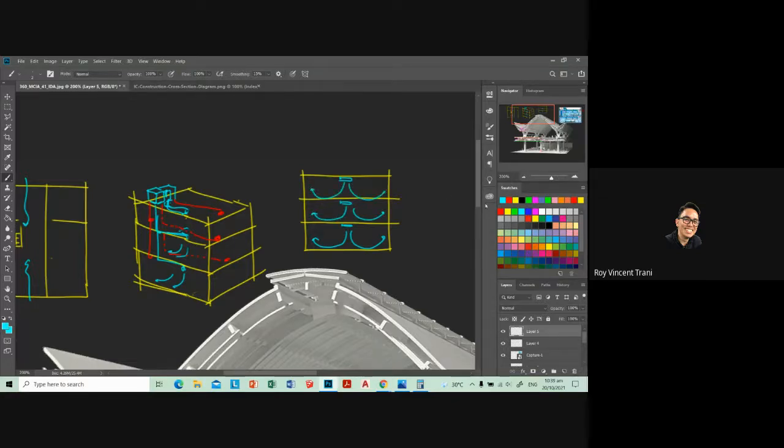And then your exhaust should be over here, maybe against the wall, or maybe you can still put it in the ceiling, somewhere over there, so they get sucked out as hot air. You see, giving the cold air a chance to move across the room. If your vents were closer, maybe the circulation of air would only be like that. So that's not good. So this part is not being cooled.